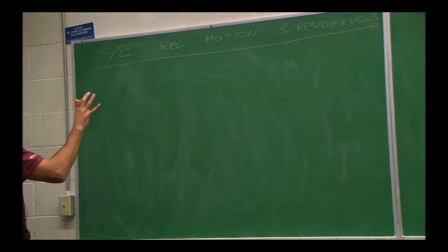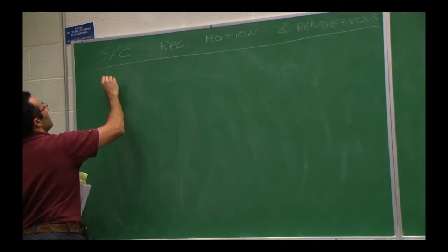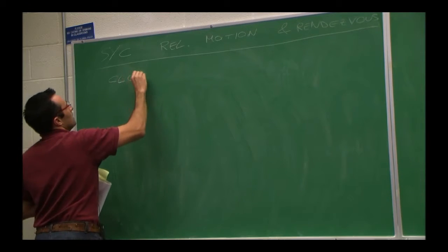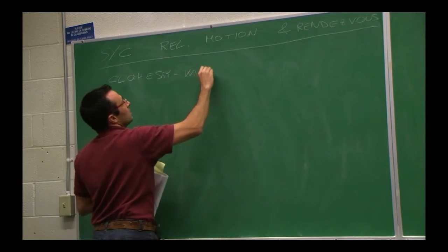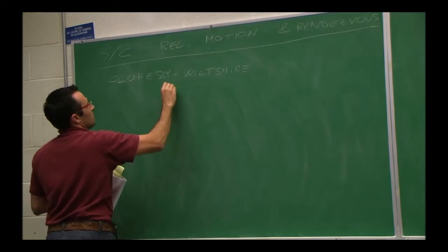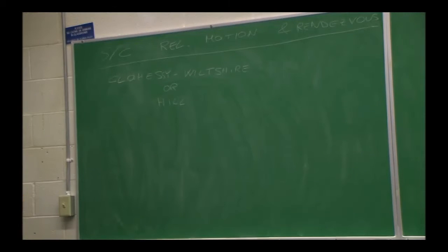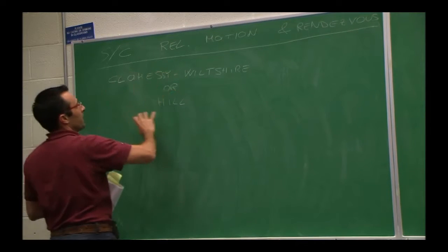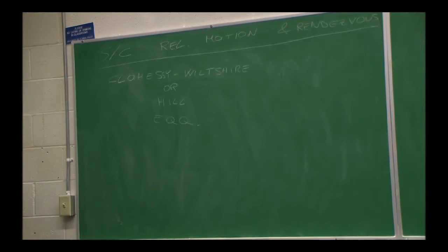So what we'll actually end up doing is finding the equations of relative motion that are called, in literature, Clohessy-Wiltshire equations. Actually, there's two names for these, because they were found independently in different decades by different people for different problems. But Clohessy-Wiltshire or Hill equations, they are linear time invariant equations that represent how two spacecraft move with respect to each other when they're close.